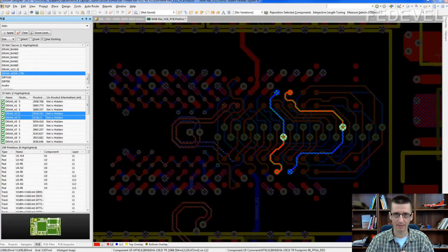Just to make it clear, if you are not sure if your design supports memory mirroring, do not use it. Do not swap the address signals, okay? You need to know what you are doing. If you are not sure, use the standard way, connect the memories the standard way.